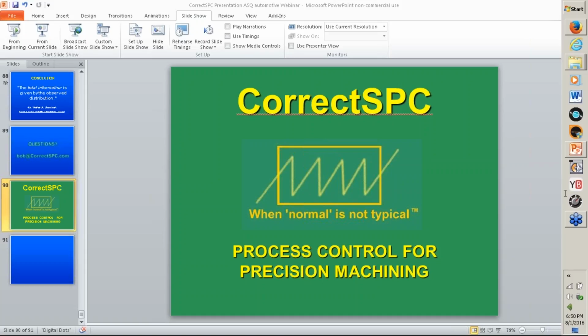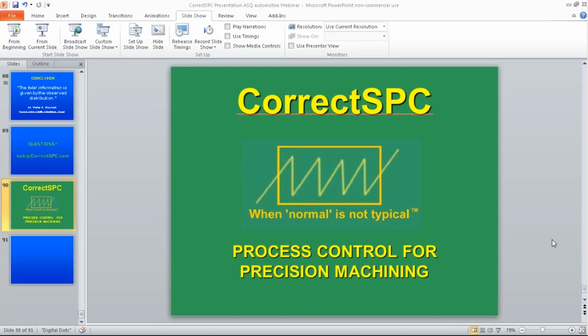Okay, I'll just start. One of the early questions was: statistically significant compared to what? Well, just in general, as far as the variation, you want to be statistically insignificant because you don't want variation from bearing wear or any of these other things to mask what's going on with the tool wear. Again, tool wear is key. That's what you want to see. And if you have bad bearings, bad loose ways, or chucks that are loose or out of control, you're not doing precision machining. Those things all have to be in control and in good shape before you can actually do this and get down to where all you're seeing is the tool wear rate.